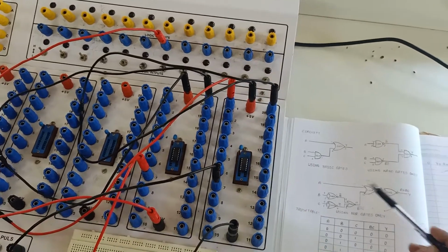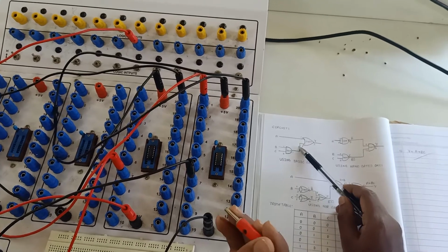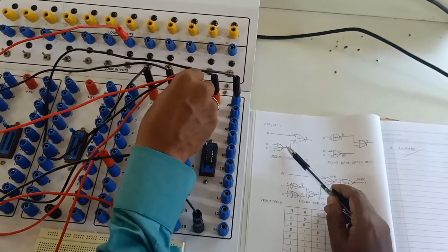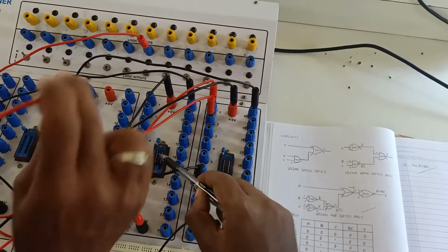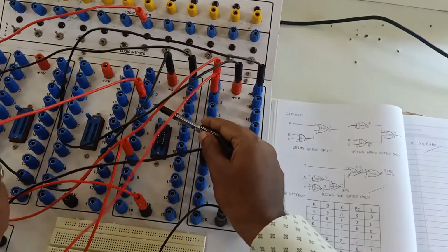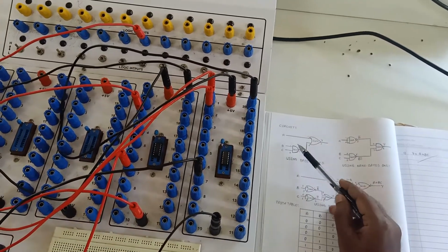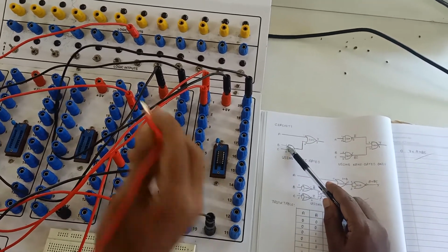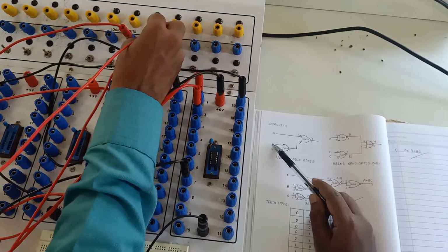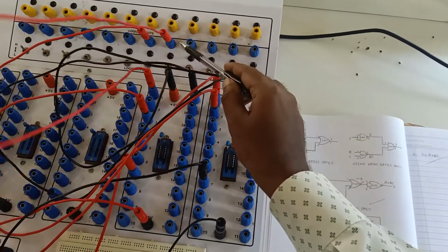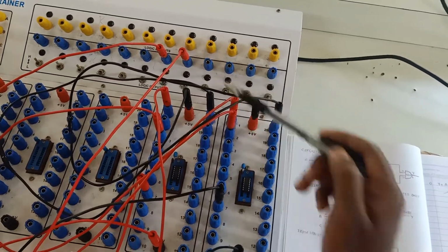Now pin number 2 of 7432 has to be connected to pin number 3 of 7408. So this is pin number 2 of 7432, right? This is 7408. Here pin number 3 is this one. So for that we should connect. Next, moving on, pin number 1 of 7408 has to be connected to where B, another input. As I already mentioned, blue lines are input. So let me consider this as B.